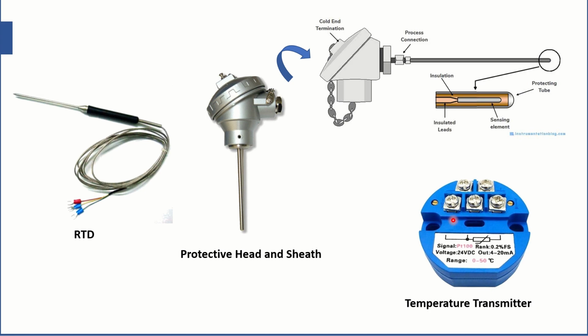This is one wire, it will be coming, it will be shorting this. You have to take your PT100 from this to this point. Now you see, while shorting, you may think why I am to short it. Actually you can see the PT100 has 3 connections. So now you have to put here the 3 connections likewise. You have to apply the supply to 2 points and you will get the output from 2 of the points.